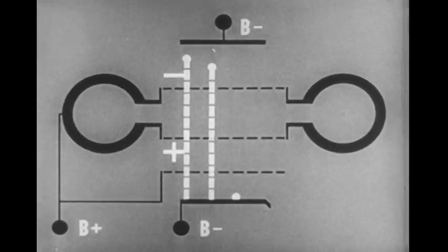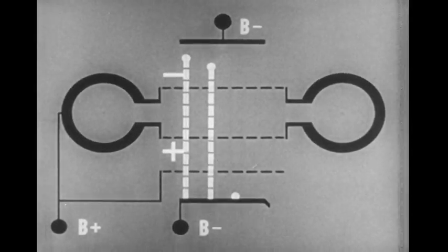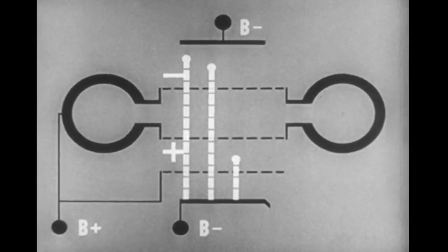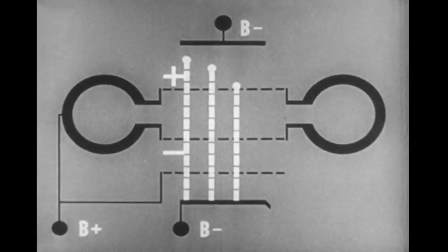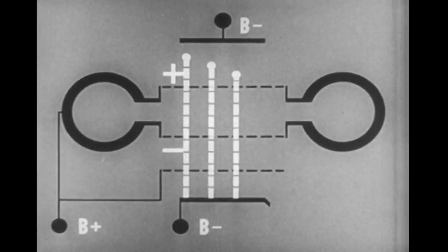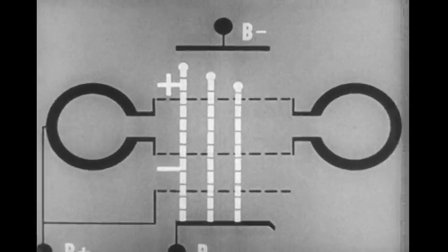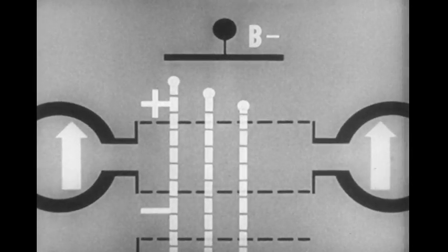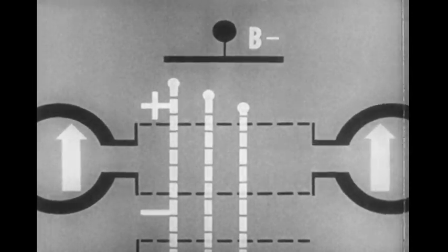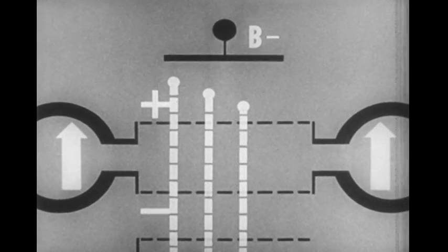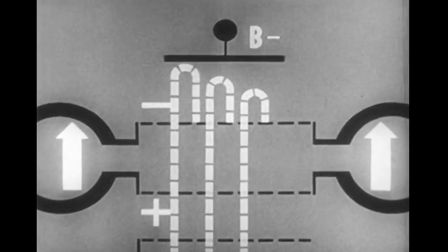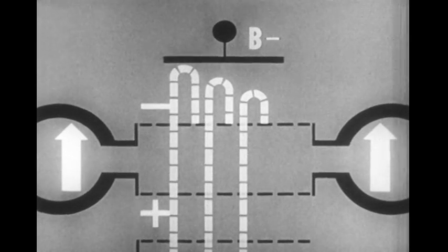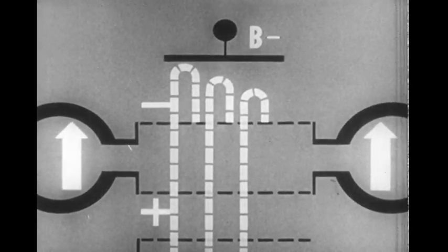The third electron, leaving the cathode still later, reaches the buncher grids when the bunching voltage is maximum decelerating, so it goes only a short distance toward the repeller before being turned back. Since the first and second electrons will have to travel farther than the third to return to the buncher grids, the net result is that they will all return at approximately the same time. This is what is known as bunching. One bunch is produced for each oscillation of the cavity.